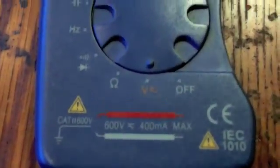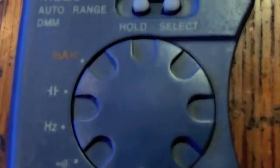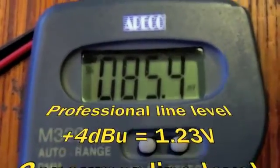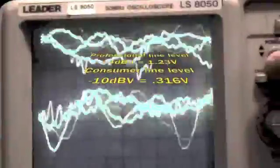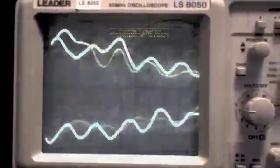0 dBu is referenced to 0.775 volts. 0 dBV is referenced to 1 volt. 0 dBm is referenced to 1 milliwatt. Professional unity gain is typically plus 4 dBu. Consumer unity gain is typically minus 10 dBV. So professional signal level voltage is typically around 1.23 volts, while consumer signal level voltage is usually around 0.316 volts. Professional signal level is approximately 4 times as much as consumer signal level.